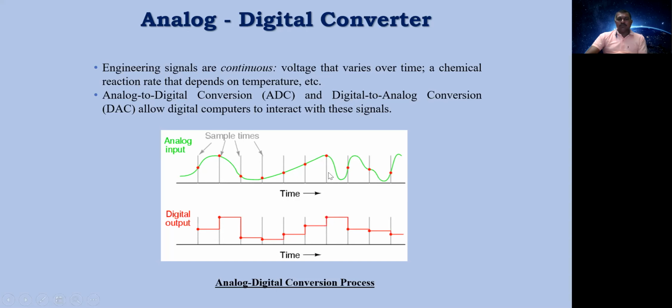Now, during this time, what happens? The signal is too fast, and the analog to digital converter is a little bit slow comparatively as the signal is processed. Right? So, what happens? This signal is being ignored, or not being digitized by the analog to digital converter, and after conversion, it directly reaches this point because conversion requires this much time. So for this, we require some circuit.